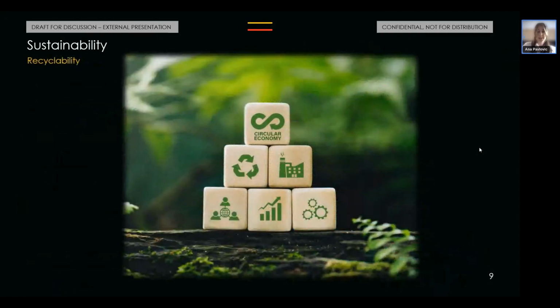Finally, if we talk about sustainability, we should talk about circularity, which stands upon several pillars, and some of them are recycling or reuse, the energy efficient or eco-efficient build or manufacturing process, as well as extending the lifespan of structures. So while BFRP as a material is not recyclable in the same way as steel is, basalt fiber is, but more importantly, BFRP is quite suitable to the concept of extending the lifespan of structures because of its corrosion-resistant properties.